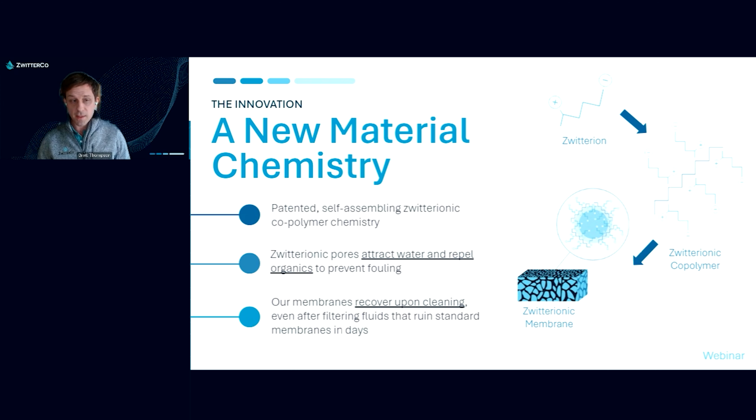This pore structure repels organics, not just on the surface, but throughout the pore structure. So even after filtering difficult wastewaters like landfill leachate, you can still remove the foulants with a cleaning.